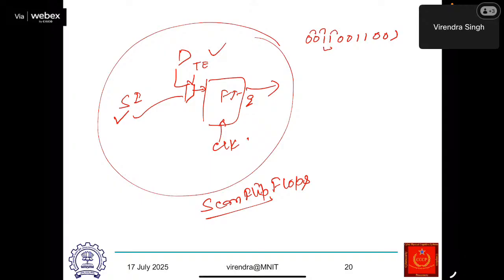All possibilities. Because there is no address decoder here, I really don't need to worry about address decoder faults, but I just need to check the faults in an array, and in an array this particular test set is good enough. We generally call that a flush test, because you are flushing this pattern all through your scan chain.